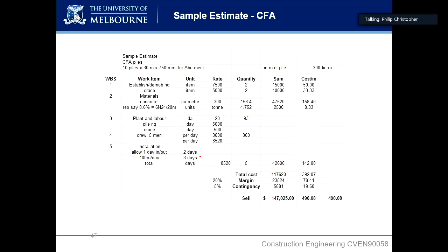Conversely, CFA piles need a pretty big rig and a pretty powerful one to drive that screw all the way in the ground. There are fewer contractors, probably a little bit less competition in the marketplace, so it's possible that they can demand a little bit more margin on these jobs. That's my guess, but yeah. But those margins of about 15-20%.